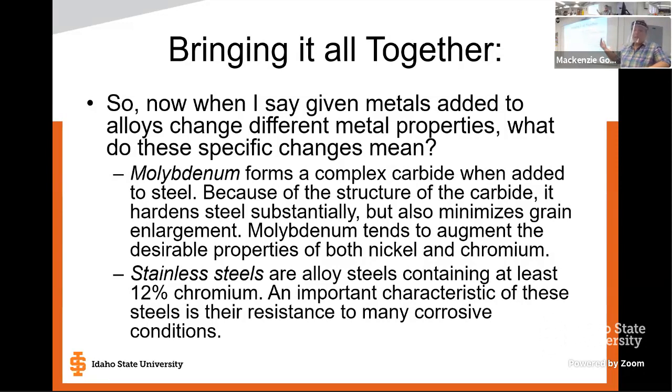There's a wear load, and you've got fluid moving through it, and it's going to be heating. So there's going to be some aspects of turbulent flow. So it's going to be rough, and you're going to have issues with erosion inside that piping system. And that chromium and molybdenum together, they're going to have a lot of resistance to erosion, corrosion, and other wear type of forces that are happening on the metal. So that's exactly why you add moly and chromium.